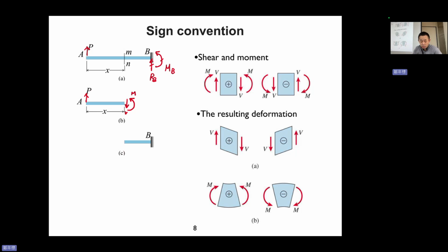That solves the balance in the Fy direction, but you will find it is not enough, because it causes a clockwise rotation. So there must also be a bending moment in the opposite direction to cancel the clockwise rotation, counterclockwise here, so that the material stays stable and achieves force balance. All right, so that's the concept. You can imagine that with a different cut, you might end up with different V and M. Not in this case, this case is too simple. But if you have other forces and other moments on the material, your V and M will change through the x.